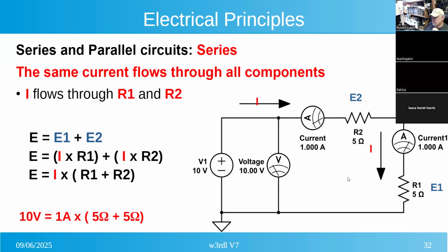So the I current, on the top of the diagram, it looks like a rectangle. The I current with the arrow going to the right over that circle with the A, where it says current 1.0, that's the amps, right? Correct. That symbol is for an amp meter showing the amount of current. If you were to put that in the circuit, it's showing that the current is the same through both of those resistors.